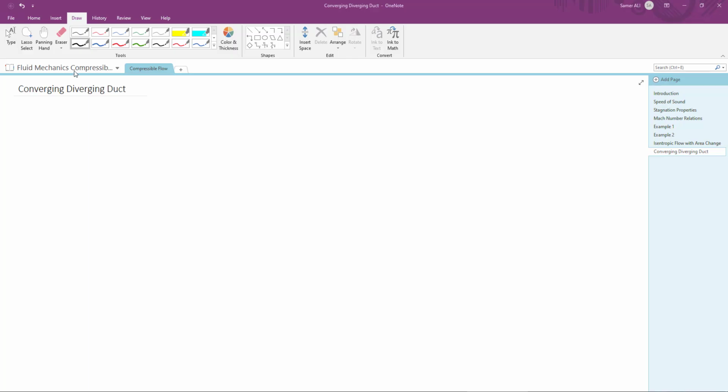Hello and welcome to this new lecture on compressible flow. In this lecture we'll talk about the geometry of a converging diverging duct, and we will start from the equation that we've developed in the previous lecture. We said that dA over A is equal to minus dV over V multiplied by 1 minus the Mach number squared. In the previous lecture we've investigated the two cases.